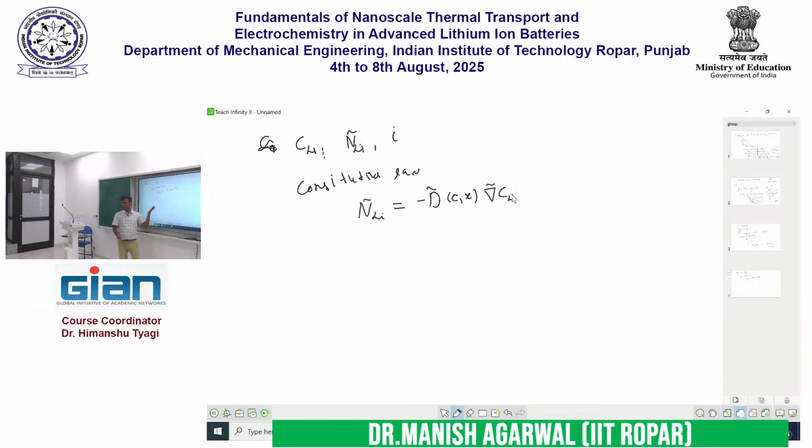You have seen this law, right? There is a name to this, Fick's law, right? So if I write it in the 1D form, it is going to be minus D into del C over del X, right? The way the heat transfer happens, right? From a high temperature to a low temperature. Similarly, if you have two species, where one place has a higher concentration and another has a lower concentration.